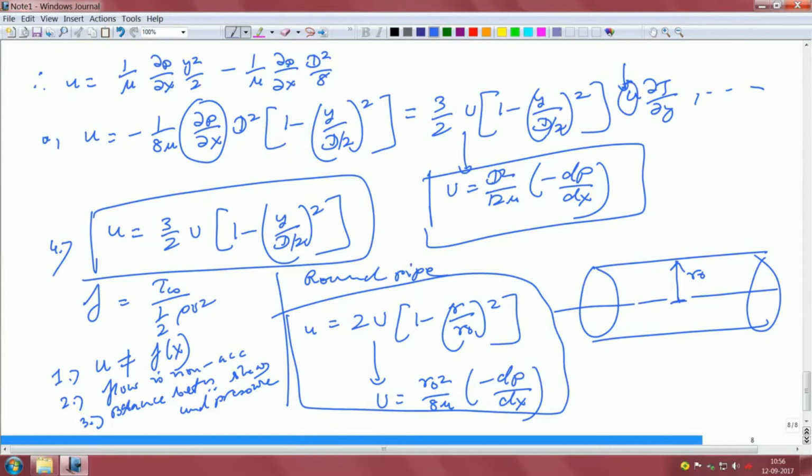You can solve it a priori, and you can take that solution and apply it in the energy equation, provided that you are operating in the fully developed regime of both the cases. That means you are in the hydrodynamically fully developed regime, and of course the energy equation is also in the thermally fully developed regime.